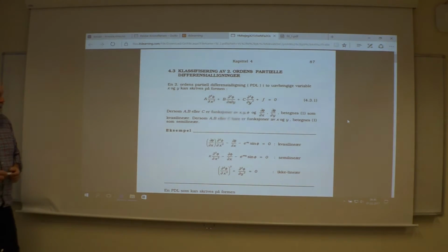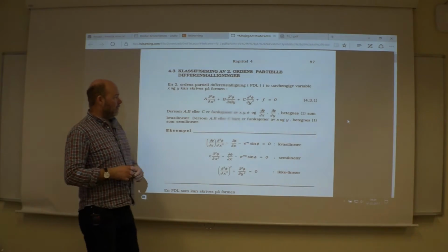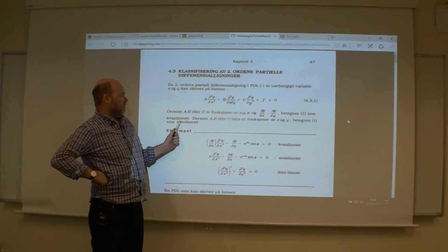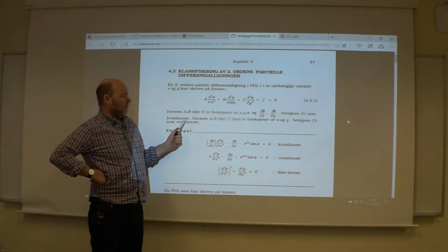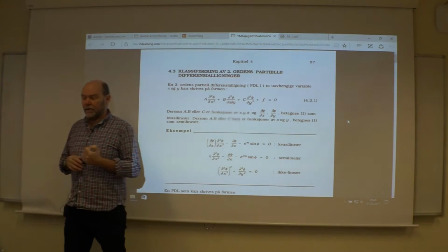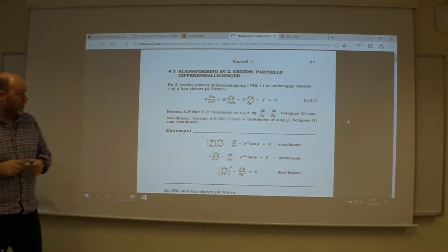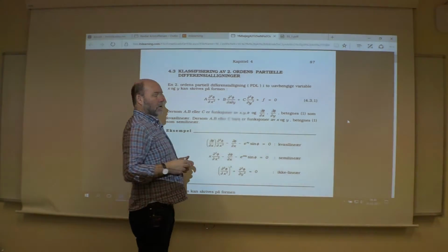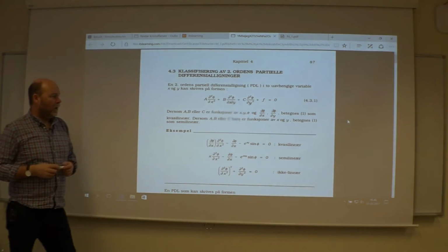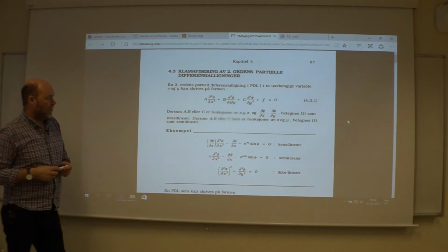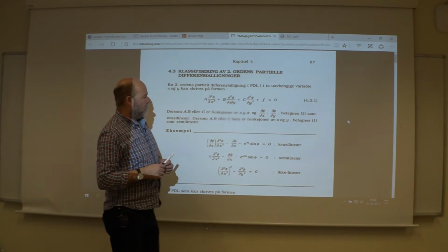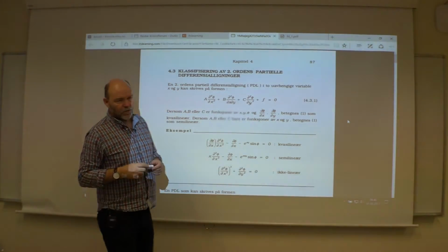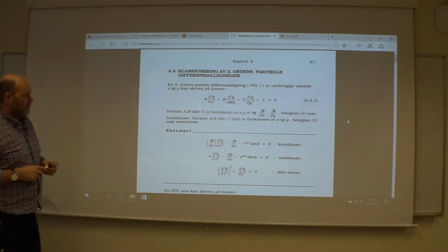And for us, we will have a sort of a quasi-linear version here of a partial differential equation, looking at the Navier-Stokes, where, as you know, you have the double derivative when it comes to the viscosity. But we have some nonlinear terms. We have some function multiplied with the derivative of functions in the convective terms. So it's a nonlinear differential equation.